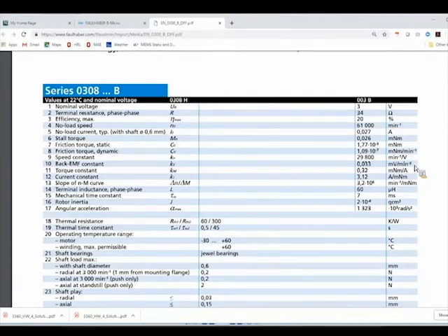So you have a motor, it acts like a generator as well. It creates a voltage across the armature or rotor coils. And they're giving this in units of RPMs, so that's not going to be the most convenient for us often. Oftentimes we're looking at radians per second. But it's basically the relationship between the amount of voltage created by that coil and the speed at which the rotor is rotating. And you'll see this information in pretty much any motor spec sheet.